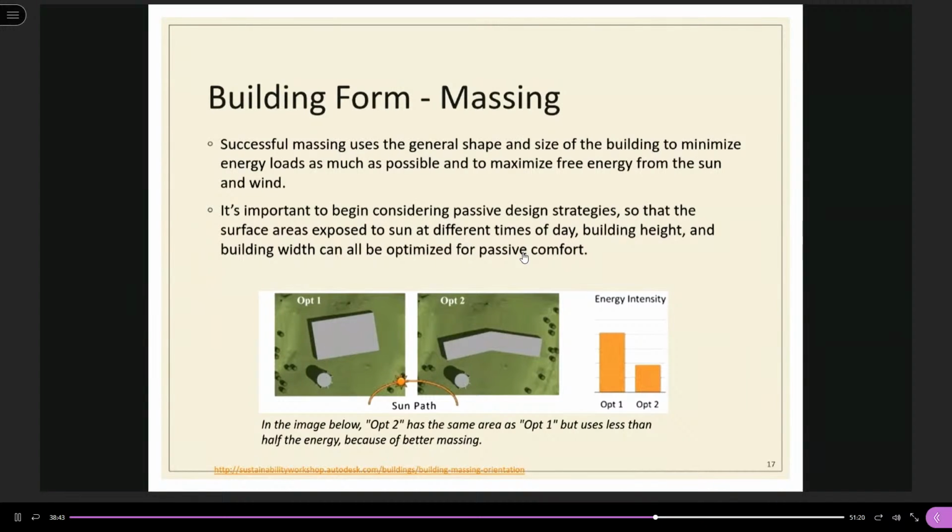This building form is rather simple, but in practice, the building form will consist of different kinds of shadings, and the layout plan will not be that regular, so it will involve a large amount of energy simulation. But after that, we can have a better idea about how this layout and the building form can affect the annual energy consumption of the building.